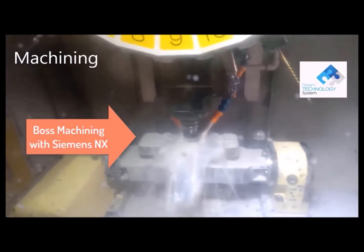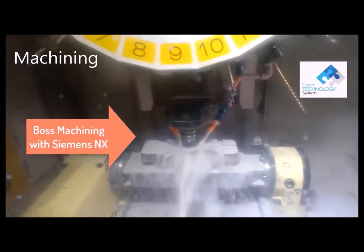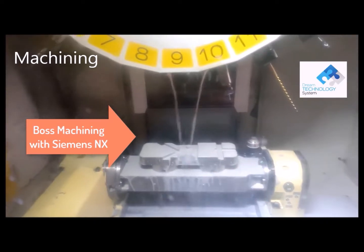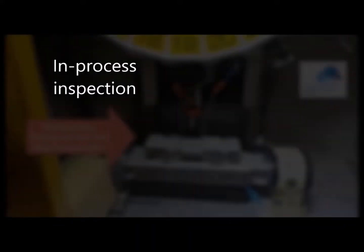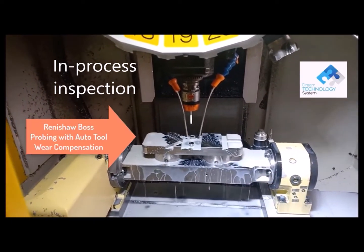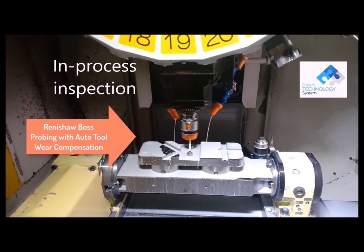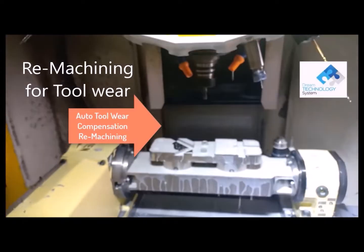In machining, for example, we can perform an intermediate or in-process inspection of machine features using a touch probe in this example. From this information, we can calculate the precise amount of tool wear. If there is sufficient wear, we can perform a second machining step to compensate for the known tool wear as seen here.